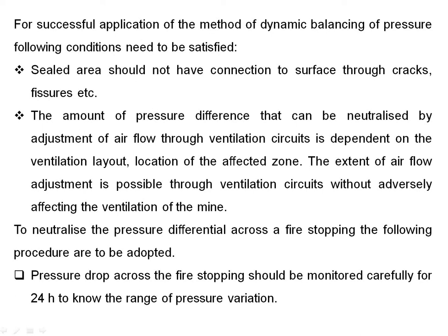The amount of pressure difference that can be neutralized by adjustment of airflow through the ventilation circuit is dependent on the ventilation layout and the location of the affected zone. So the extent of the airflow adjustment is possible through ventilation circuits without adversely affecting the ventilation of the mine. When you are thinking about the airflow circuits, it depends on the ventilation layout and the location of the affected zones, and that is what tells you the chances of the fire or the fire zone.